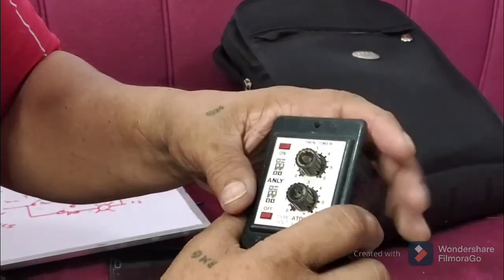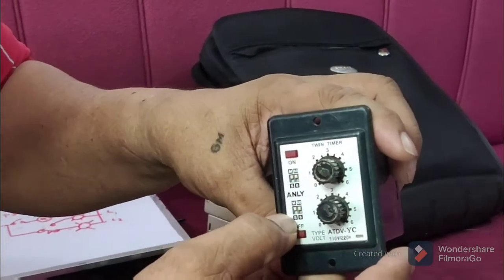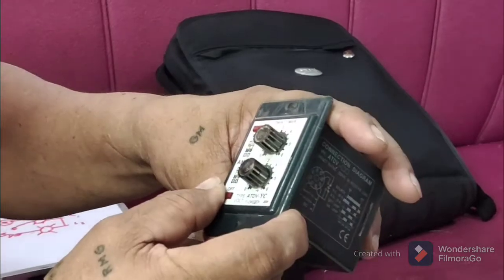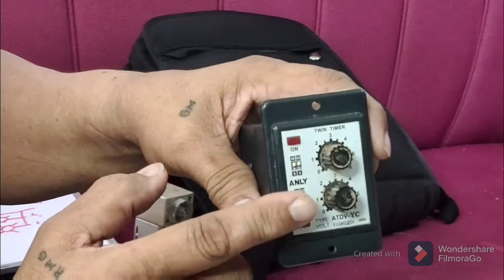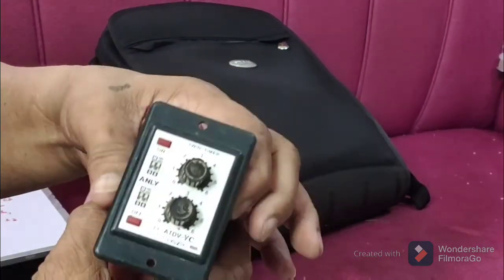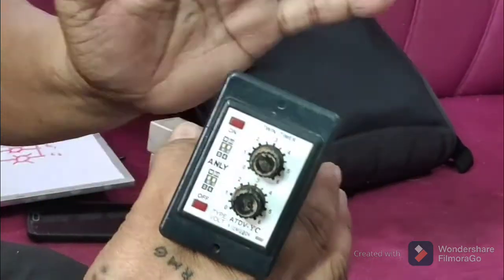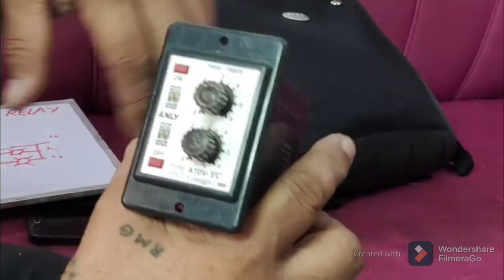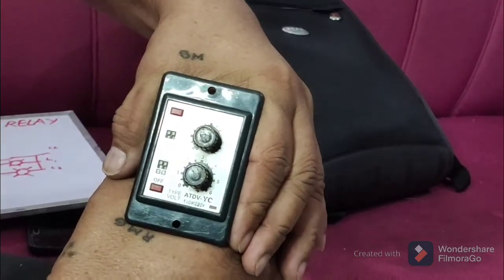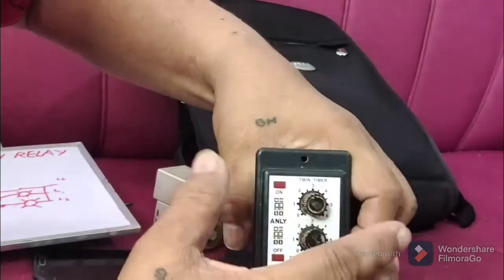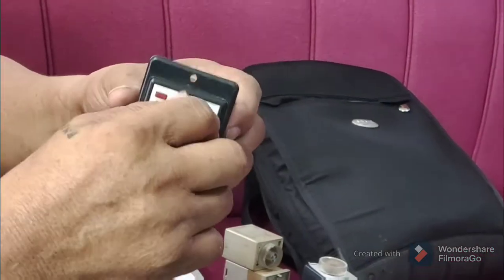So how to connect? The same. So you have your adjustment here. It's still programmable. If you want to make it 60 seconds, 60 minutes, 3 seconds, 3 minutes, then you have this kind of timer. This is a flash type timer. You cannot mount this immediately. There's a need for you to bore a hole, and then this is the one that will appear in your control box. This is a flash type. Okay? So the principle is the same. Only that you have the adjustment here.